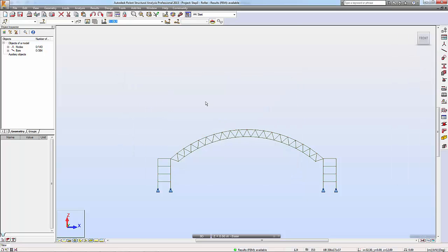And the last thing I want to do is show you how we actually can do a compatible node, but actually we put a spring into this connection, which means in the horizontal direction these two are not free, so there's no free movement, but instead we put the spring in between, so that allows the whole structure to move laterally.